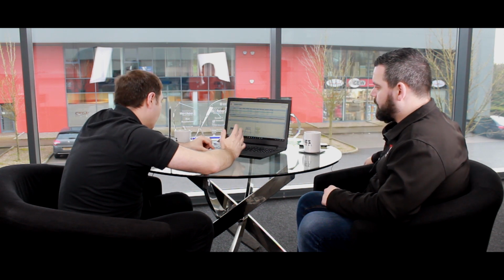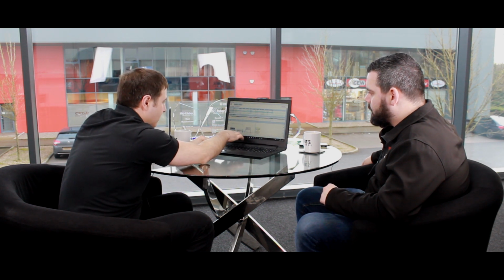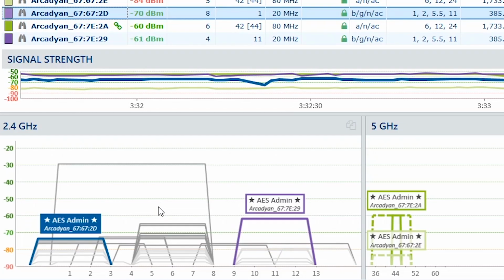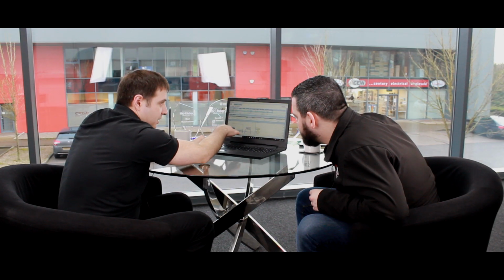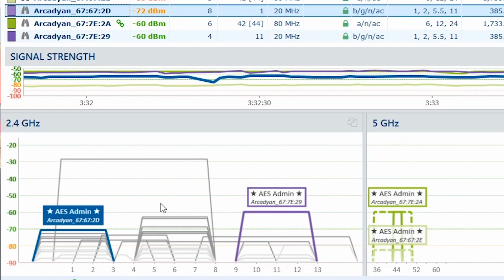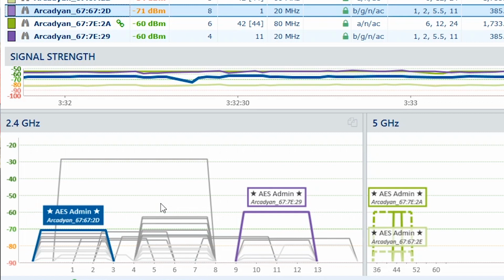So what you need to do is find a clean channel. At first look, channel 8 or 9 would be clean, or maybe at the top. You wouldn't go between 4 and 7. I'd avoid anywhere between 2 and 8, actually. It's cleaner on the top end of the channels.